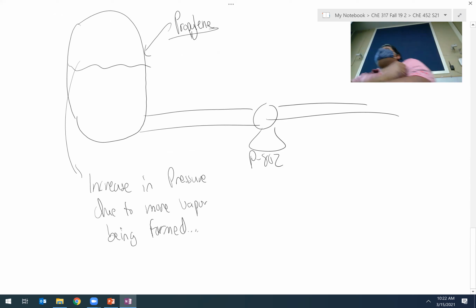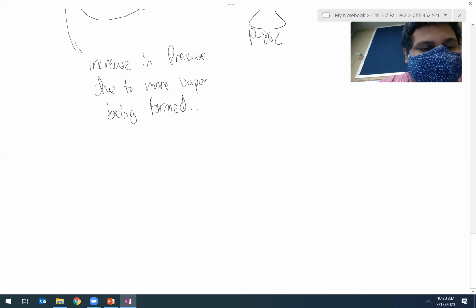Okay, so I buy that. It works. So what's that going to do to the system? What should I look at a little more closely then if I'm seeing the pressure being manipulated? Well, I'm probably going to want to take a look at NPSH and see if that's going to be changing as a function of temperature and this estimated increase in pressure.